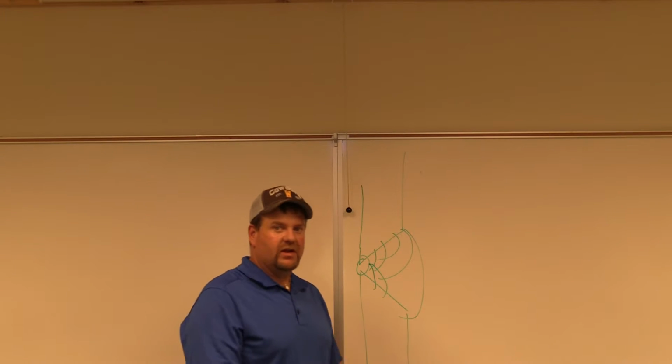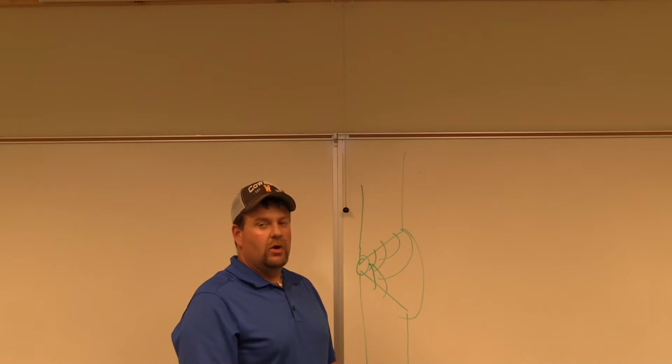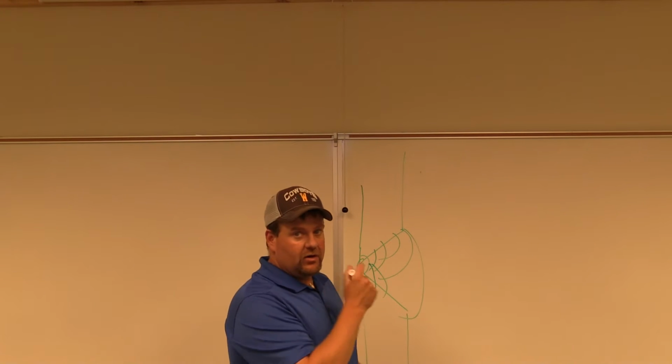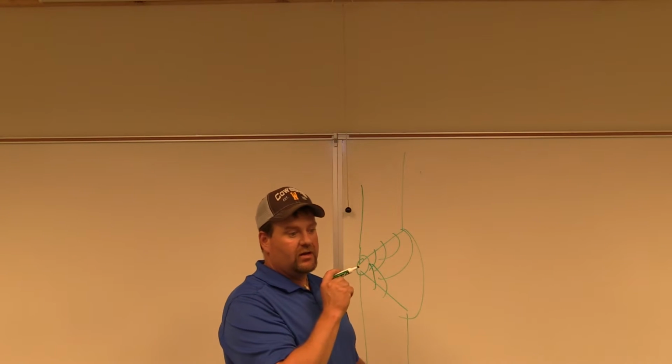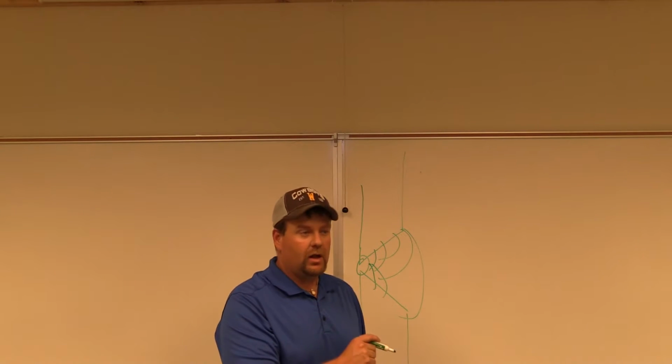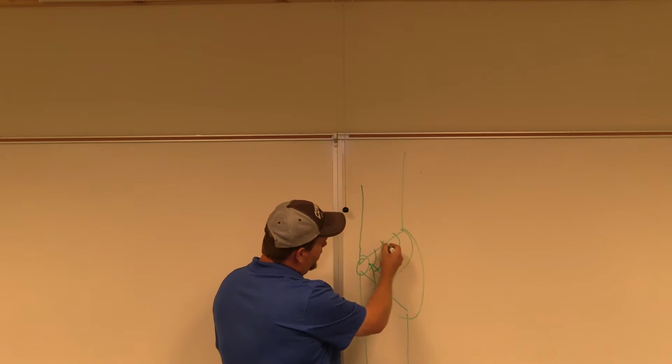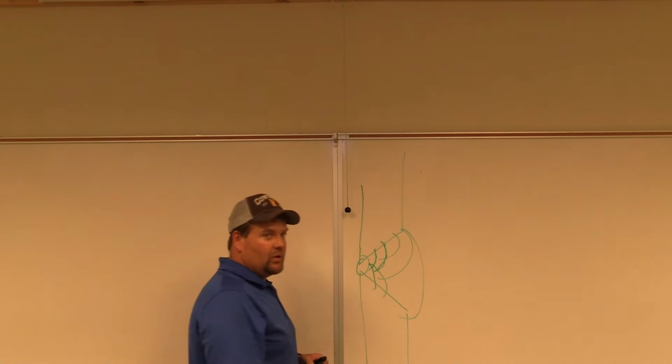And this is where bend testing is really pretty amazing. What you're going to see happen, and I've seen it on mine, and I've seen it on the welders that helped teach me how to weld as well, is you're going to see these welds start breaking right here at the toe of each one.